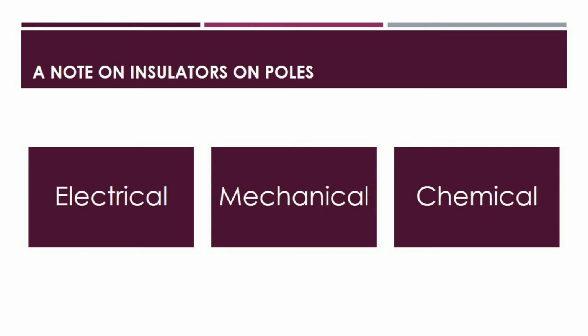Rolled salt, freezing rain, and snow accumulation on the insulator surface in some locations can cause flashovers, which can lead to insulator dielectric failure. Electrical flashovers can harm porcelain and composite insulators from the outside as well as the inside.